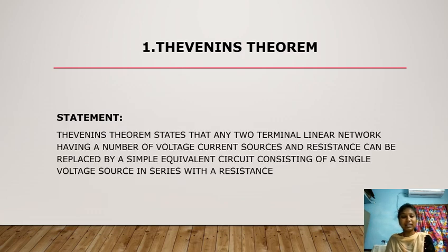Let us start. Thevenin's theorem. The statement is: Thevenin's theorem states that any two-terminal linear network having a number of voltage and current sources and resistances can be replaced by a simple equivalent circuit, consisting of a single voltage source in series with a resistance.